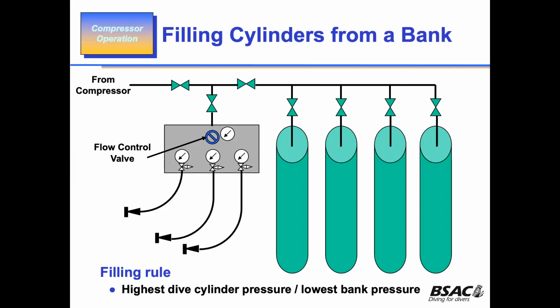So that way you run the lowest pressure bank, and you get as much out of the lowest pressure bank as you can on all the cylinders. And then you come to the next one and you work along, and then the next one and you work along. And then when you charge the cylinders up, they all come up together. All right. So that's it.